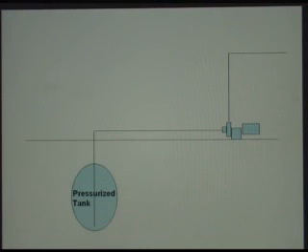If the tank is underground, physically below the inlet nozzle to the pump, and is pressurized, depending on the pressure inside the tank and the specific gravity of the fluid and the elevation difference, this could be self-priming, it may not be. If there's enough pressure to have the fluid rise beyond the pump, then it becomes a self-priming system. If the fluid only comes up this high, then it's not self-priming, and you have to figure out a way to prime it.